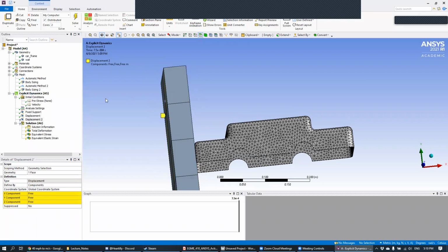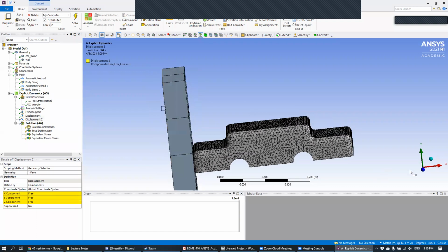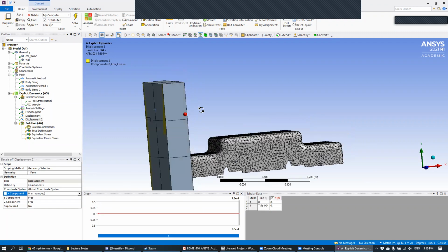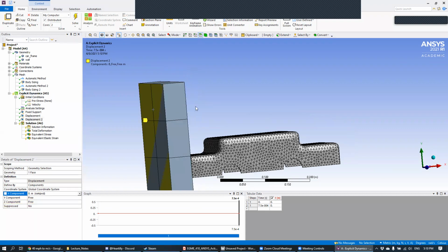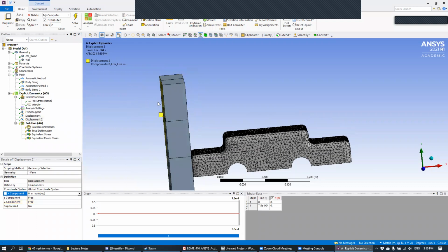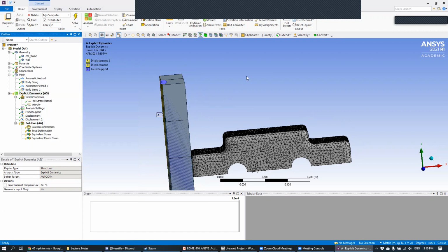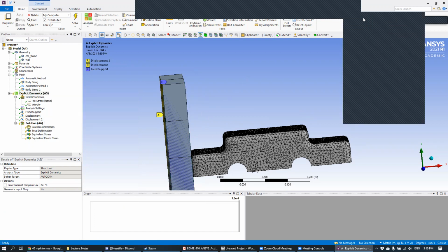If we had another wall that's symmetric on this side, ignoring the car, but let's say that wall is doubly thick, we want to make sure that we don't have any displacement in the x direction. So we set it to 0, and that prevents any displacement into this plane or out of it, and then we'd be able to apply our symmetry condition that way. But I think if you're doing a static simulation, there's an explicit symmetry boundary condition here. I think it's just not here because it's a dynamic simulation. Yeah. Gotcha. I see. Okay.